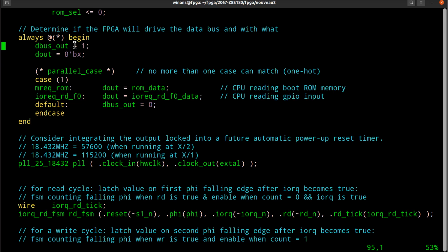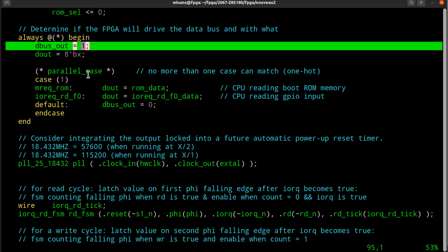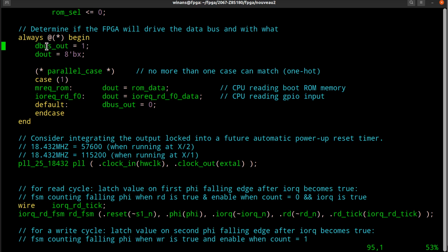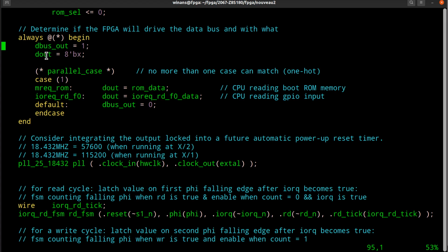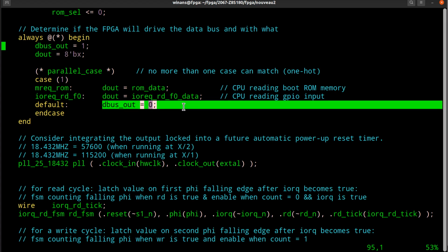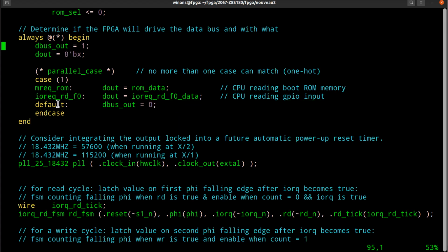Now what happens is by making the default a 1, I don't have to set it to 1 down here with begin, end, and visually screw this all up. Assume that I'm going to output, and I don't care what's on the bus. By putting it here, I don't have to put it in here, which gets rid of all the begin-else down here around the default case. So this is real easy to read, really summarize it, okay?